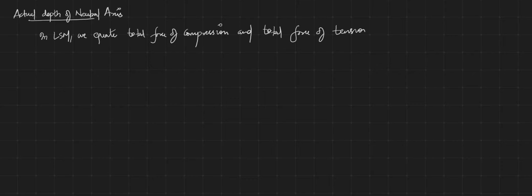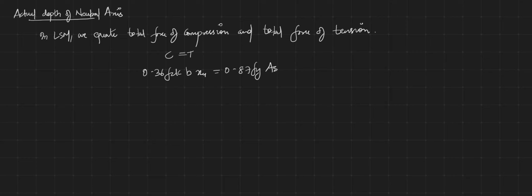That is, we'll equate C is equal to T. Your C is 0.36 fck b Xu, and your total tensile force is 0.87 fy Ast.